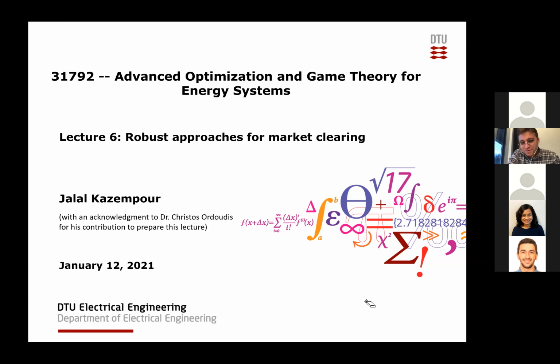As you see, there's no scenario index there. So let's say for a single point, which point? What is omega here? Omega is our wind realization. So under wind realization W, not omega, W, we are clearing the real-time market. And note that all the day-ahead decisions are fixed. They are known in the real-time stage.